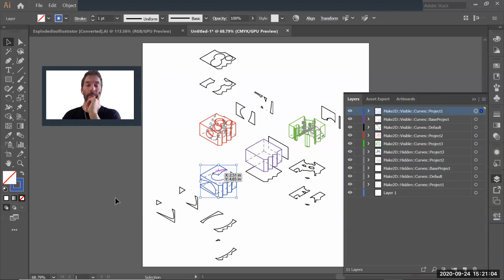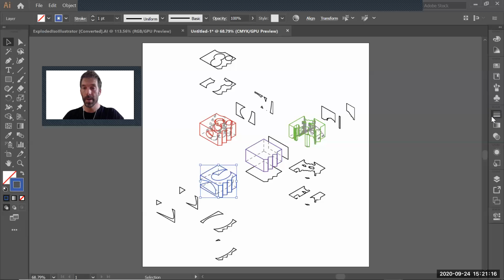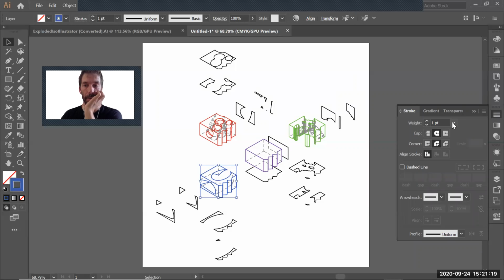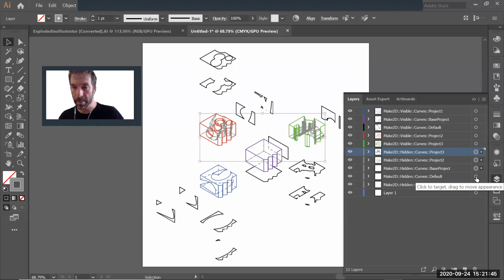This is the visible lines for the blue, maybe that's the color you want, maybe not. What I recommend is you go to your first panel and say, well, that project is red, so you change the red color for it, no? Regardless, you're gonna have to adjust a little the thickness, maybe a little less, a little more. And definitely the hidden lines, notice how big they are. You need to maybe select all of them at the same time, which you can. You can select pressing Shift from hidden and then Shift again here. No, that didn't work out. You can press Control, sorry, one by one.